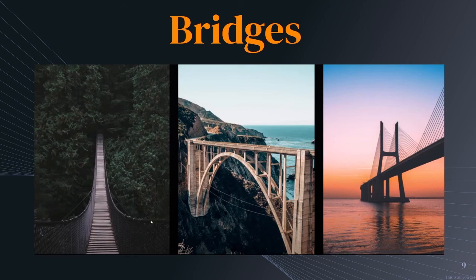Bridges, another example of repetition. The wires, the grid on this one, the planks, all very easily replicated, and then you can attach it to a spline that runs this whole thing and defines the shape. To adjust it, if it bent over too much or you wanted it to sway, you could animate the spline for the sway, or you could tighten it up by pushing that spline vertical, and then it would look more like a flat, tighter bridge.